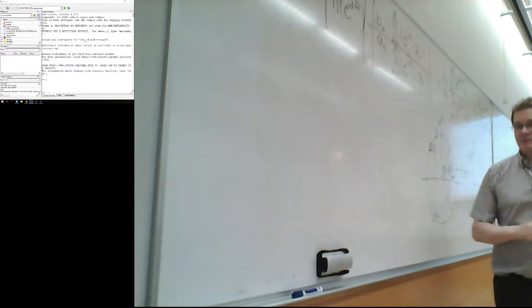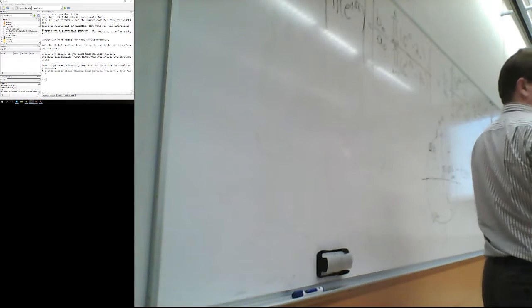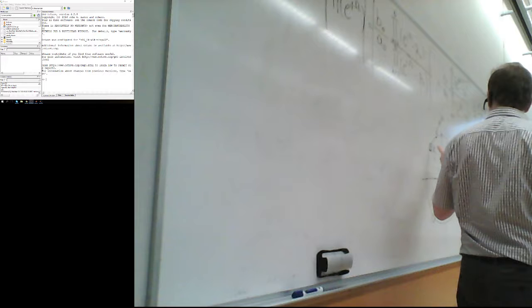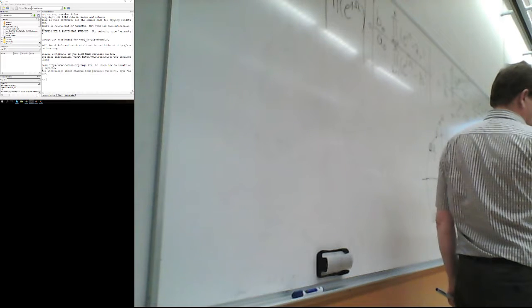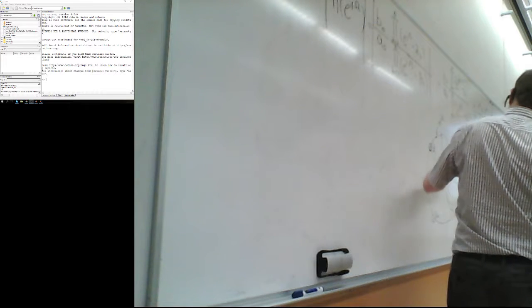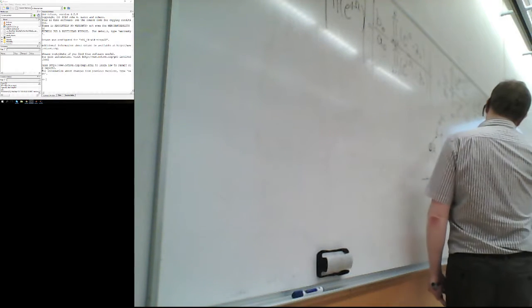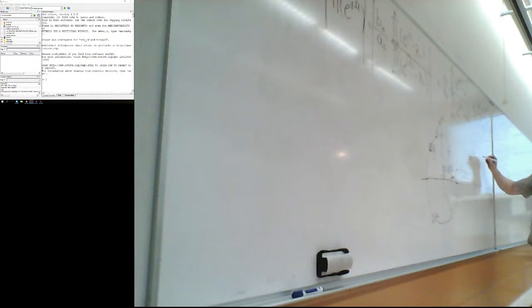So those special points there are the location of zeros. Zeros of an IIR system are located on the unit circle to give the local minimum. You need suppression of some frequencies exactly on that point. And then these poles are located somewhere closer to the unit circle to add some gain. So that's caused by the pole, that gain here, and this one is the zero on the unit circle. Got it? Simple.